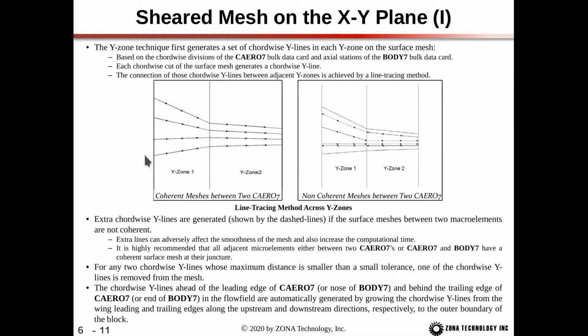That's just too many boxes and it's more modeling effort. So what I'll do instead is just have 20, for example, or maybe even 10 boxes from the leading edge of the wing to the trailing edge of the wing. But I'll still make sure that those 10 or those 20 cuts perfectly align with the cuts that I have in my wing.